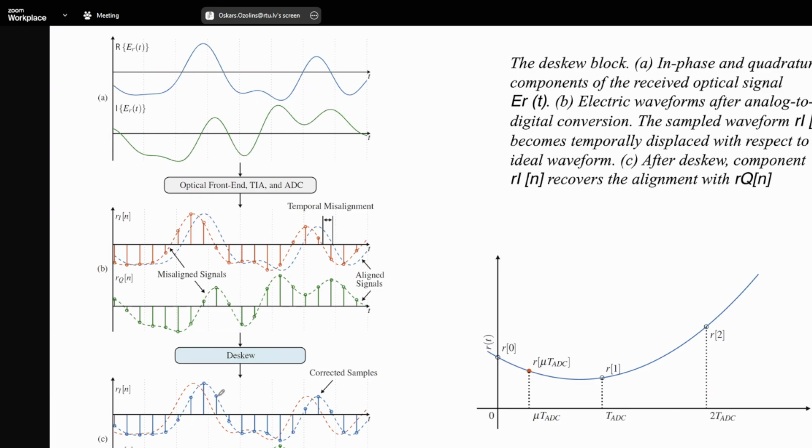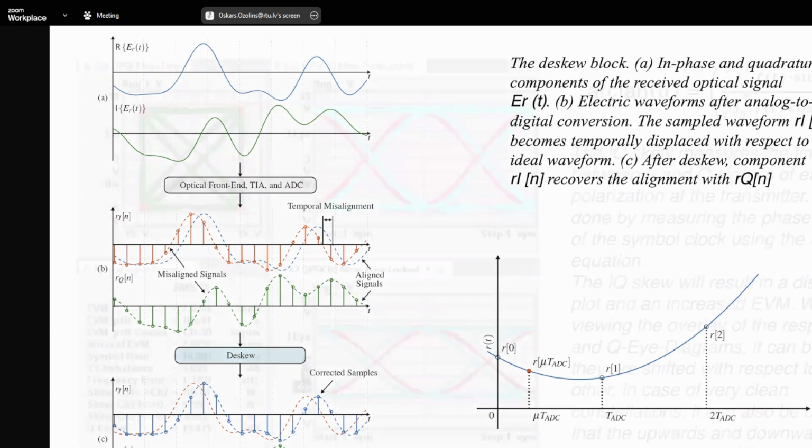So it's really a shift in number of samples, and then we still get this 90-degree difference between I and Q. This is done by shifting these samples and then finding the minimum. I tell this in basic words, but this algorithm is slightly more complicated, so you can read about it more in the book and in some relevant literature.